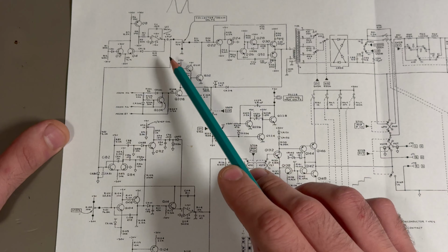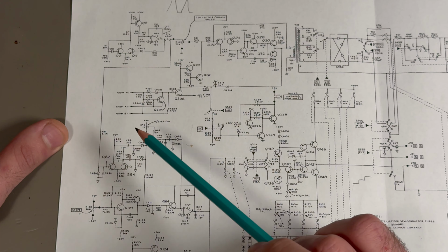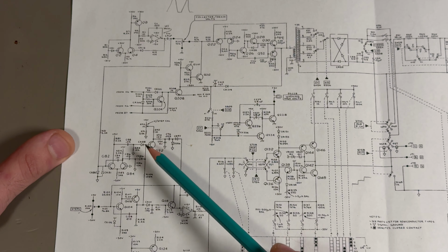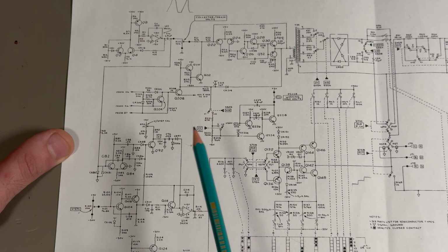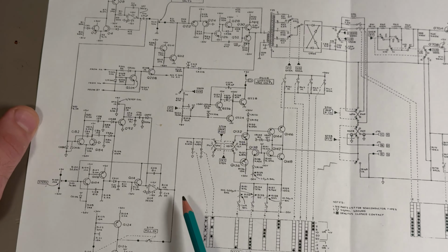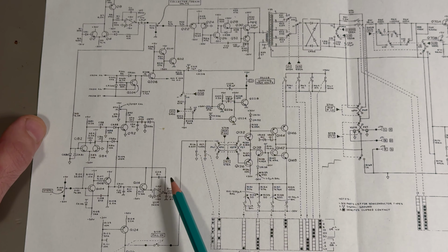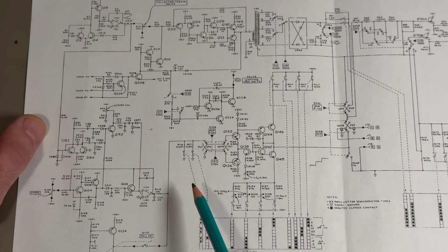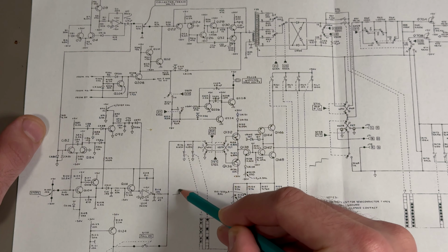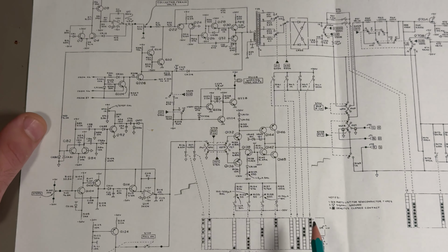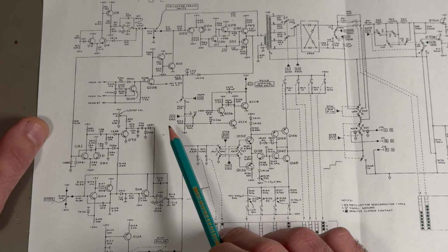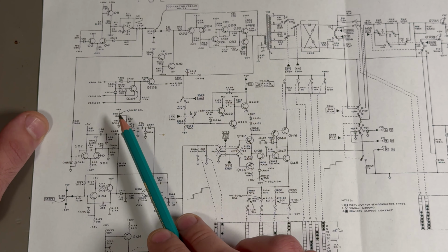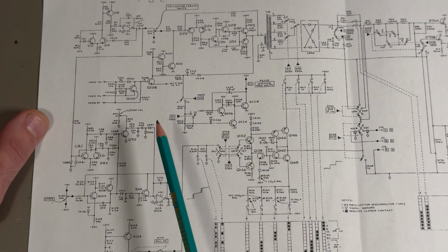So every zero crossing, this is a zero crossing comparator, every zero crossing, this circuit here generates a bunch of charge, like a quanta of charge that is yanked out of this integrator here. This is an integrator. You can see there's a capacitor in the feedback. And every zero crossing, so you don't get distortions in the trace and stuff like that, you get a voltage on the output that jumps up by a step. The amount of voltage that it jumps by per step is kind of fixed, but you can calibrate it internally. There's a trimmer inside that you can do that.